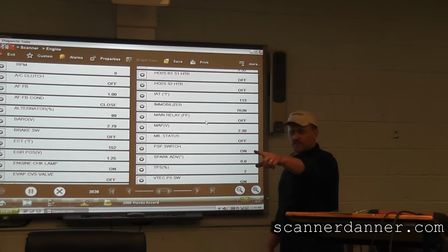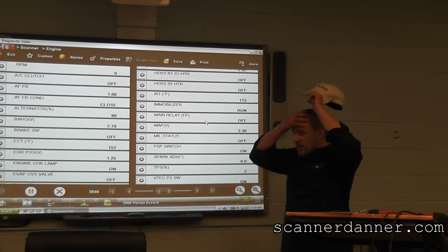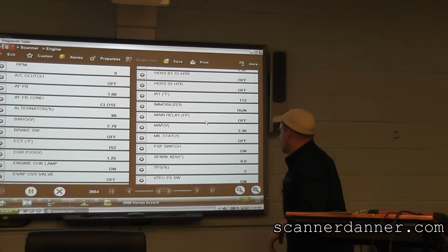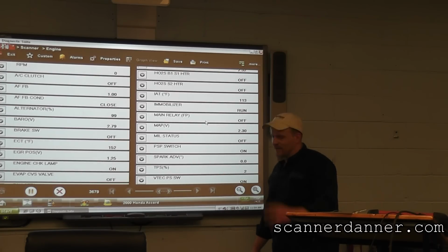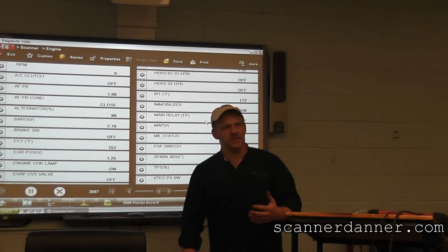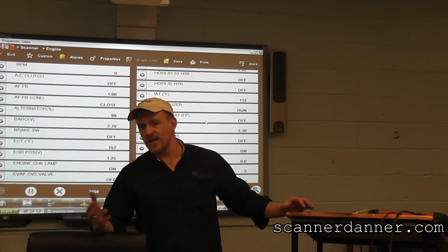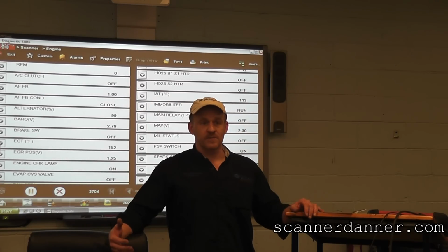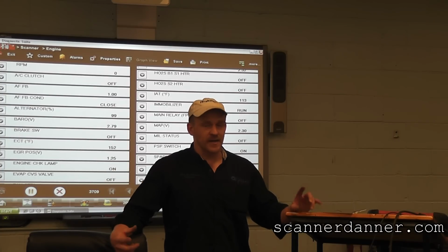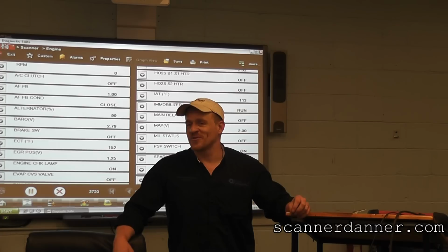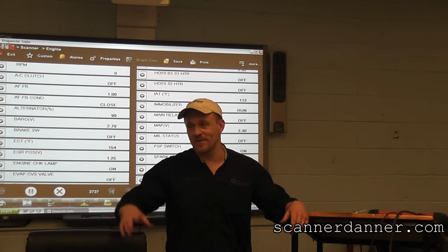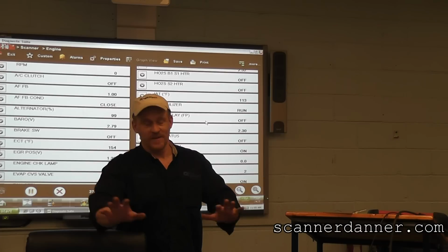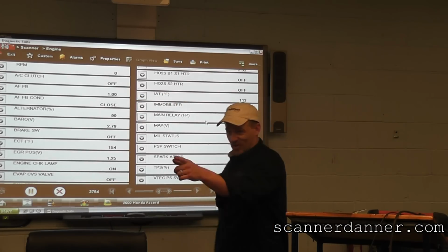You mentioned something moved, Tom. What did you see change? Yeah, the throttle position sensor. That moved when I unplugged the MAP. 14%, 15%, down to 2-3%. Nice, okay. One of the things I was thinking about in between this is this had an engine put in it. Is it possible that we had some connectors that were reversed and that the TPS is plugged into the MAP and the MAP's plugged into the TPS? If that's the case, then if my TPS, that's a good observation.